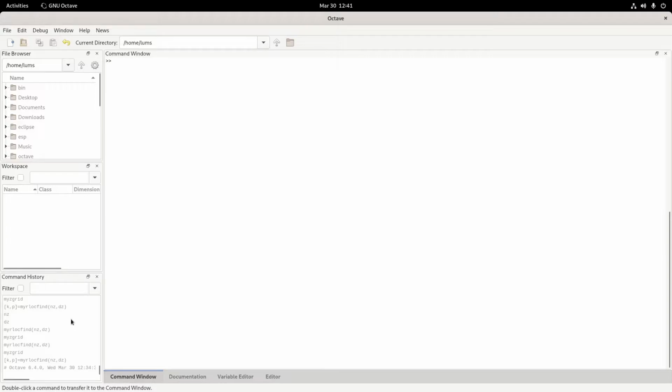So this is an interactive IDE, very powerful, and you can do a lot of things with this Octave IDE. So it is not necessary that you need to use Jupyter, because especially if you want to do interactive actions like picking out a pole or picking out the gain in a root locus plot, it is better to use this Octave environment.